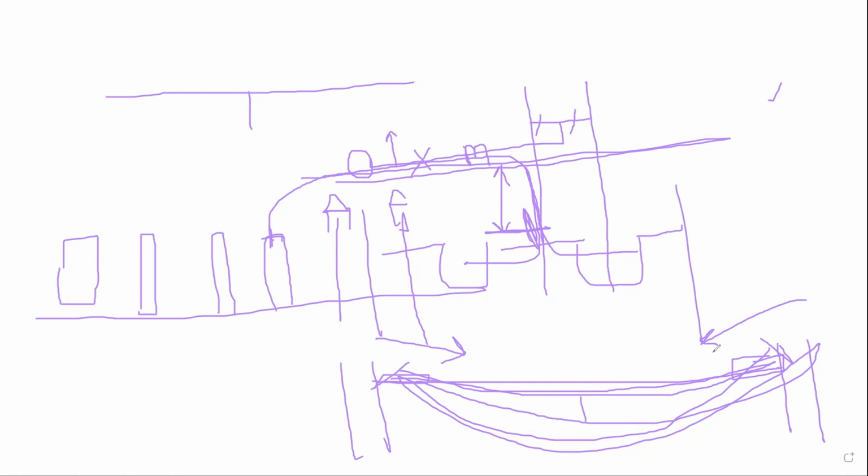Suppose I am applying 10 kilonewtons of tension, that structure should be capable of handling that tension. So the selection of the structures will be completed. After that, the sag also gives the required clearances for the down conductor. So for everything, we need to calculate the sag. That's it.